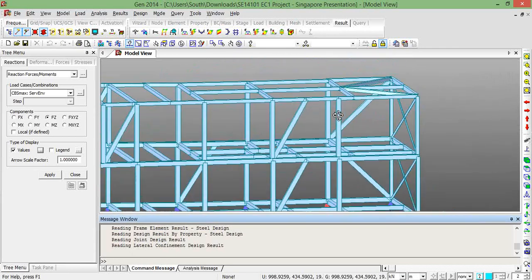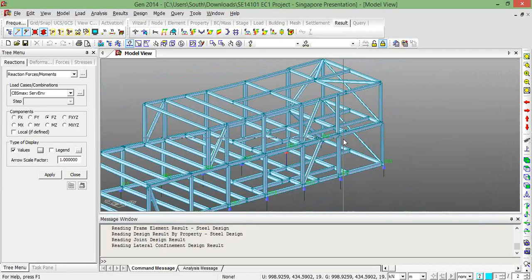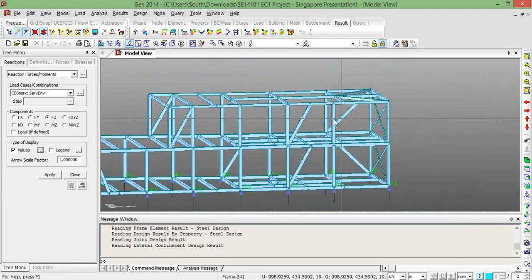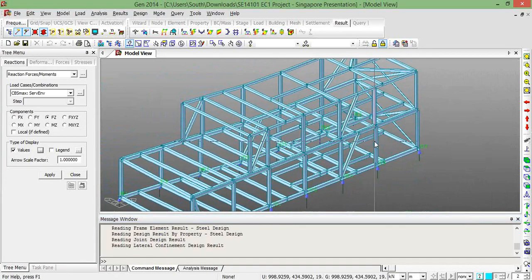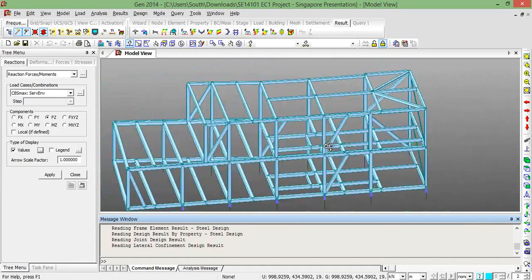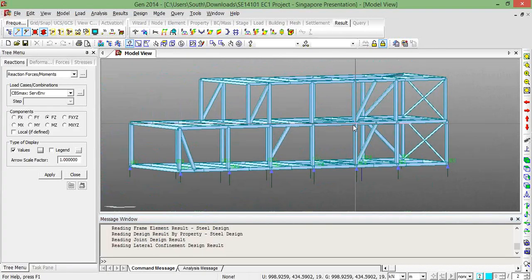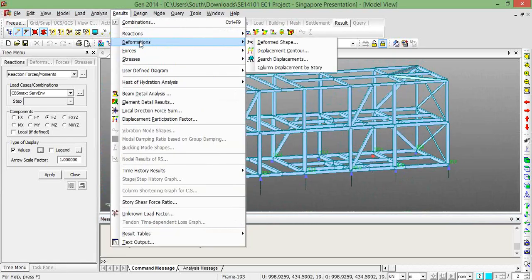We tried to also bring back some stiffness by having another column here, taking out some of the moments, the moments due to lateral forces, just after the intended glazing section. However, everywhere else seems to have full frames that have come in, so we're usually okay there. So if we just show what the lateral sway looks like.